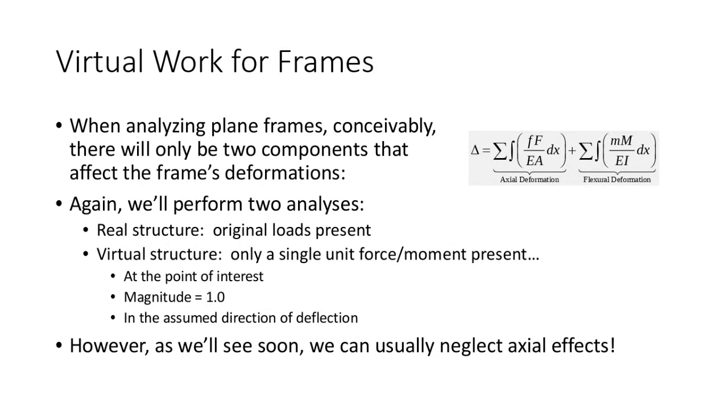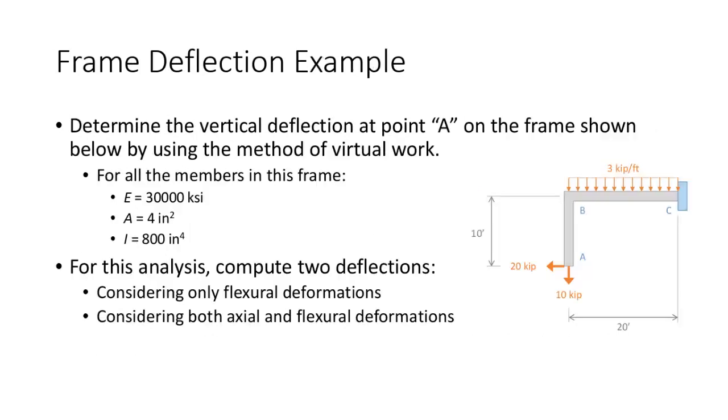However, what you'll find is that when you actually look at the numbers and you look at the proportion of answers that you get for frame analyses, you can usually just neglect the axial deformation term and just not worry about it. In fact, on your homework assignment, I'm going to have you compute a frame deflection, and I'm going to tell you just do the flexural, don't worry about the axial. But in order to convince you of that, I have a problem here I want to work through.